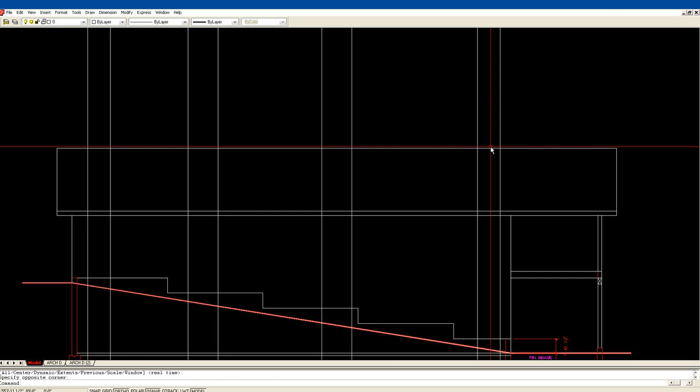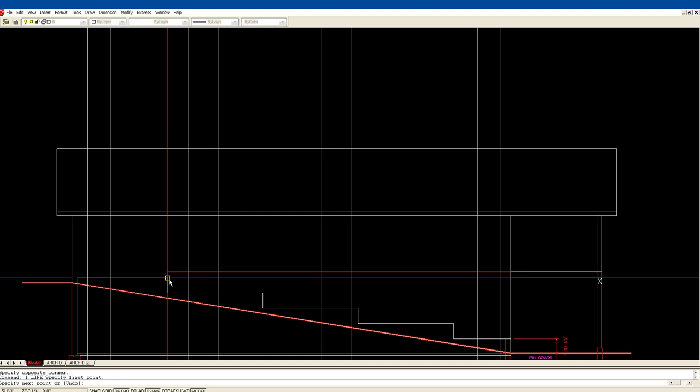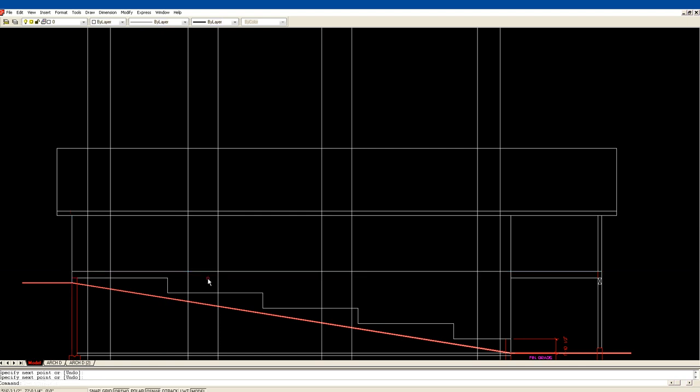We have to establish the height of these windows. So I'm going to put this line back in. This is our top of floor. And typically, doors and windows are 80 inches off the floor. When we get into doing the cross section, we'll actually show how that window at the top is built. There's 2 plates, we know that, we talked about that. And then we'll use probably a 2x10 header on top of it, an L1. So it'll be 2 2x10s nailed together.